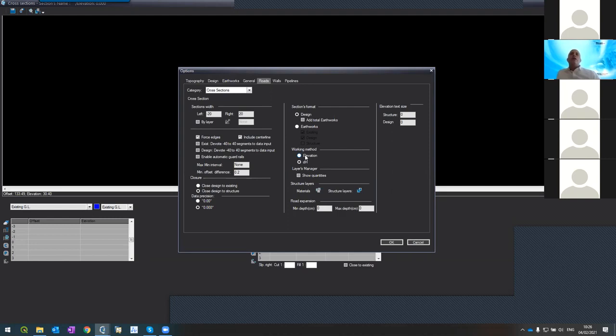So I think it was Doreen that asked me earlier if I'm calculating between 2 roads, where I got the design from someone else, just to calculate volumes, then I will use elevation. This time around, I'm the designer. I've already defined my profile, so I'm using DH, and I will use a template to design my cross sections.